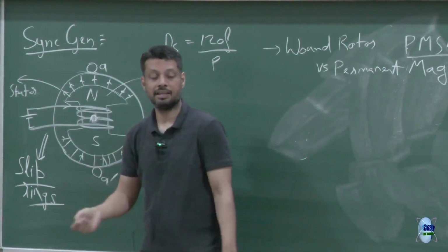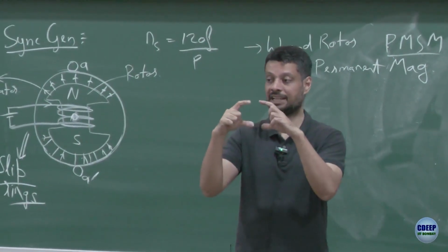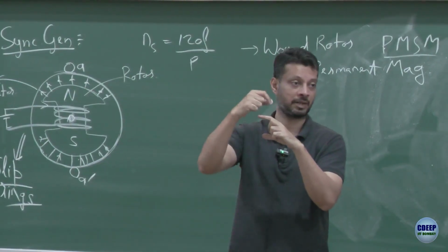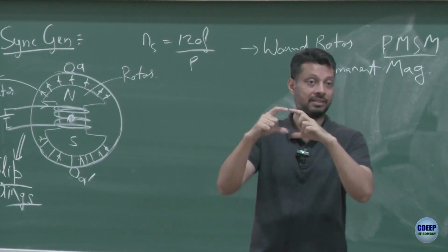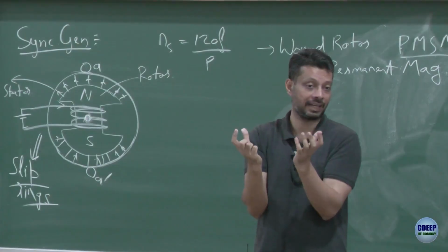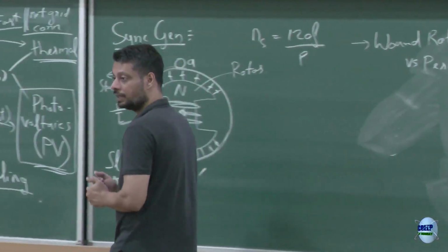A slip ring. It's not brushes and commutator. Brushes and commutator had two different electrical sections, right? Sometimes the brush was connecting this part, sometimes the brush was connecting this part. This is a slip ring. The whole ring is a single section and the brush always touches the whole of the ring, right? So it's a slip ring. It's not a brush and commutator assembly, right? Okay.